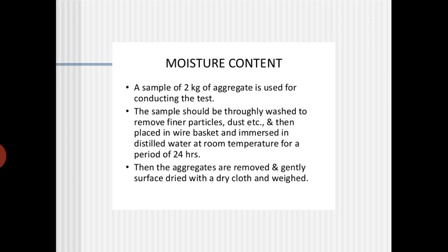What you can do is take the water sample which consists of total dissolved solids, then pass that sample through filter paper. Whichever particles are retained on the filter paper are neglected, and some particles will filter through. What kind of filter paper do we have to use here? Normally we use Whatman 42 filter paper to filter this sample.